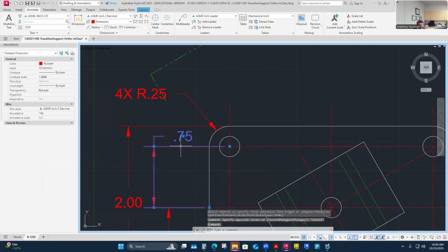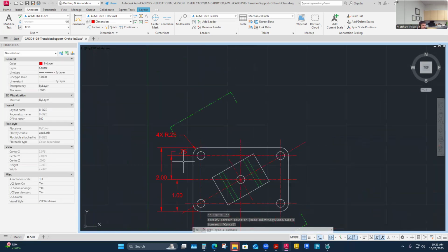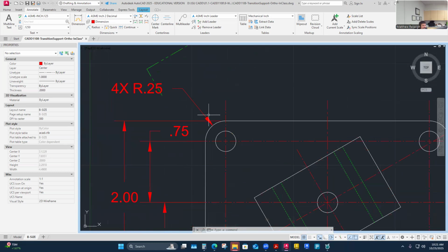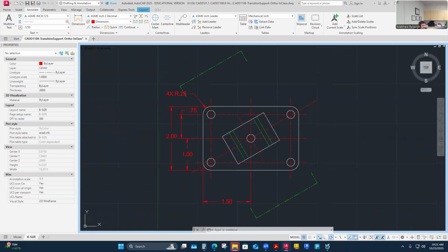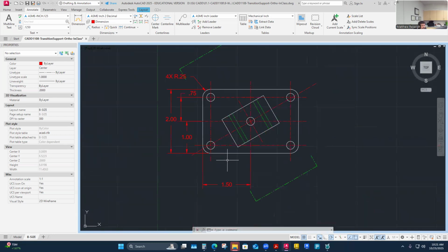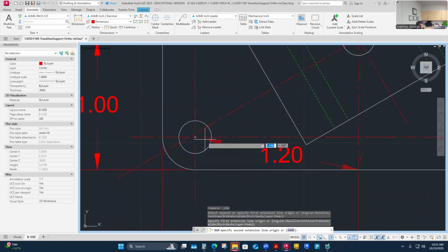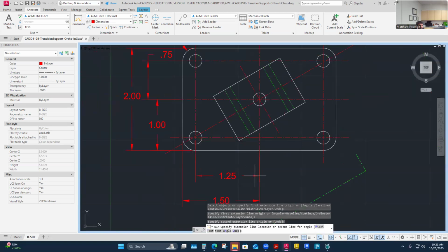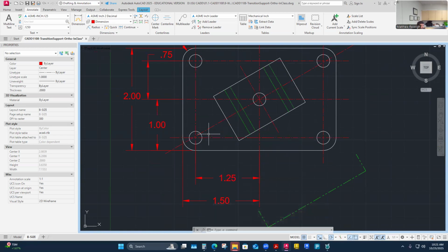Of course, I don't want that to overlap. I need to tuck these back to the object edge like that. Let the center line do the reaching. So that's located in Y direction, and I just need to locate it in the X direction. So I'm going to do that from this center, though. And I could do that in between views. That'd be okay. Maybe I could do it over here, but it does relate to the relationship between there, and I have room here. So let's dimension that location from this center to here, right? I know it seems like I'm working off 2 different holes, but because of my already establishing those center line relationships, I'm able to only do minimal dimensioning and make that apply to all these holes.